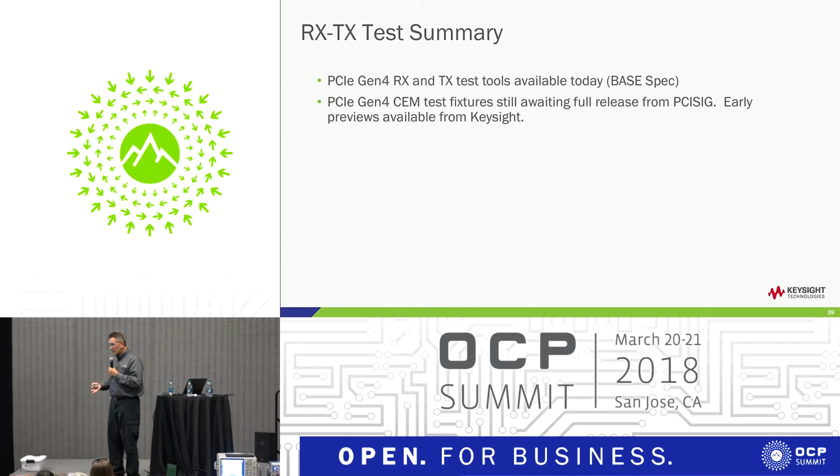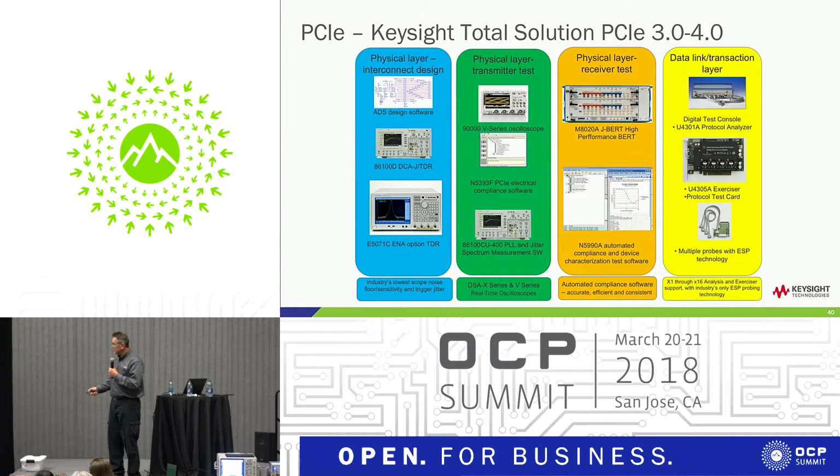The calibration process for a system test, like you see here, is completely different. It's similar in that we follow the same overall approach, but the actual targets and the methods for how we put together the jitter cocktail are a bit different. So both of those testing tools are available for PCI Express testing for Gen 4.